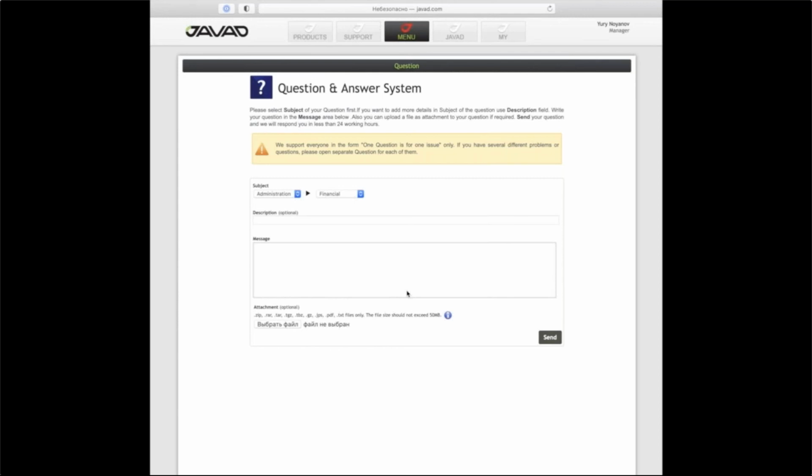So we should be careful with the settings to get precise coordinates in RTK. When you run your own base and your own rover, the setting is not significant, because you can use the same setting for base and rover, and you will receive correct coordinates. But when you use a third-party station like VRS or other base stations, you should know and indicate in which reference frame the base station is working, and set this information in the rover.